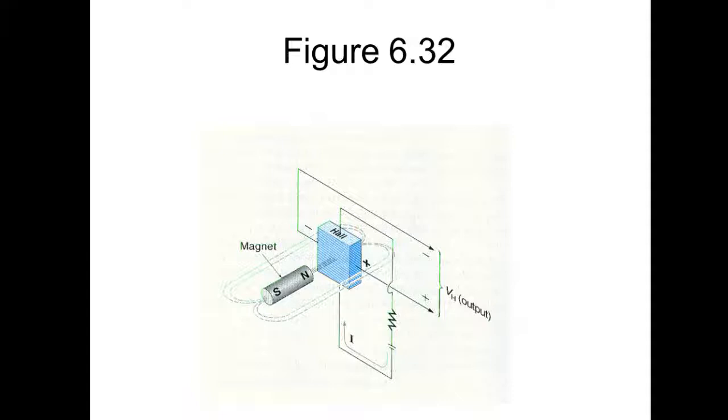So a magnetic reed switch, if you've got enough magnetic field, it's going to close, right? But it's not actually sensing the strength. With a Hall effect, we can actually use that to sense the strength of the field. So you can buy analog Hall effects, which sense the strength of the field. You can buy digital ones, which are going to trip at a certain threshold.